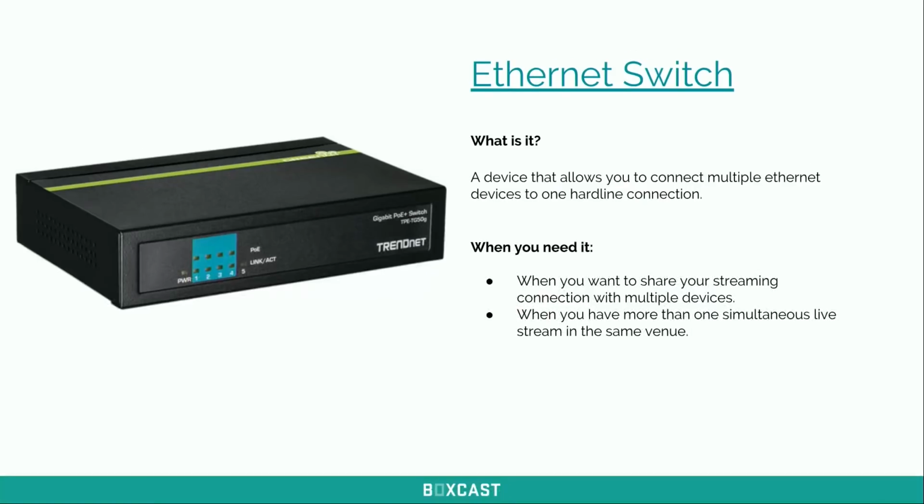And then last but not least, for live video streaming, we really recommend getting an Ethernet switch. The advantage of an Ethernet switch is it allows you to connect multiple Ethernet devices to just one hardline connection. Anytime you go to a venue, you're likely not going to get 5 Ethernet cables to one device. You probably just get one hardline that the venue or the convention gives you, and you're going to have to split it 5 different ways. So this is kind of like an internet version of a splitter.